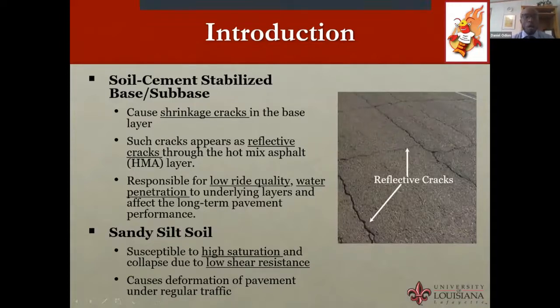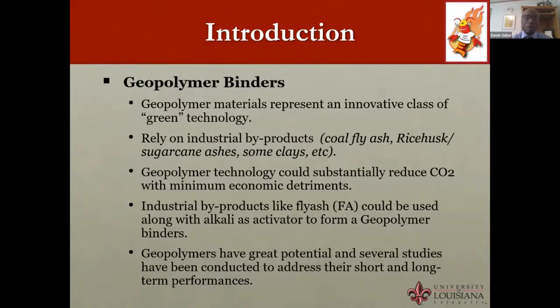We also know that sandy silt soil, when subject to a highly saturated state, tends to collapse due to low shear resistance. And this tends to cause deformation of pavement under regular traffic. So what are we trying to do about this?